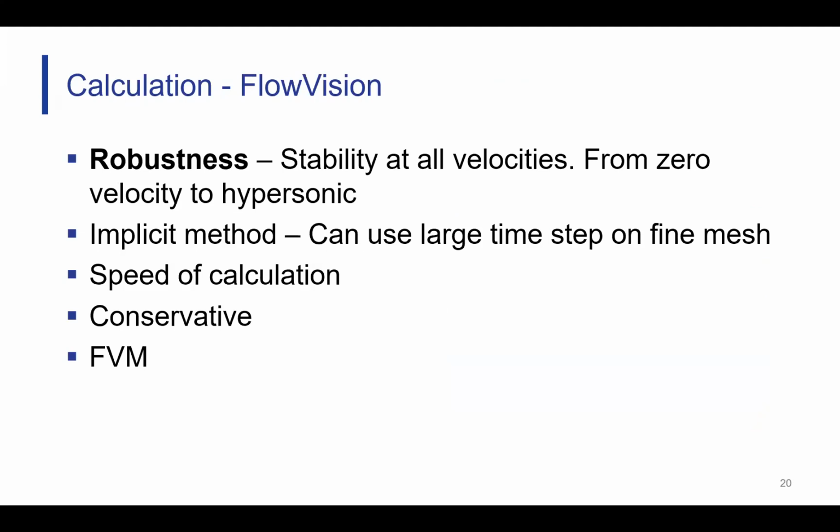And this is because solvers are very complex. They're fussy. They're sensitive to the formulation that you've put in. All of the choices and all of the decisions that you've made up to this moment, they will affect how well the solver reacts to the problem and the accuracy of the solution that comes out. The first period of working with any CFD code is pretty much trying to find where you've done something wrong, and it's always operator error rather than solver error.